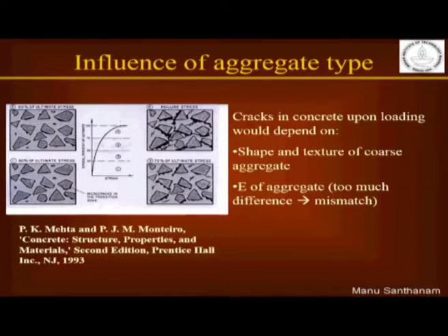So irrespective of what aggregate we have, we need to make concrete, and we need to work through the understanding of how aggregates and cement paste together behave, and we have to understand what kind of role this actually plays in the actual mix design process itself. As you all know, mix design means that we are trying to achieve a combination of workability and strength. Increasingly nowadays, we are looking at mix design to also look at durability of the concrete.